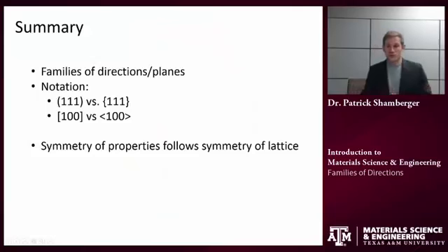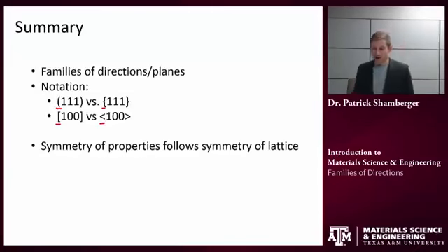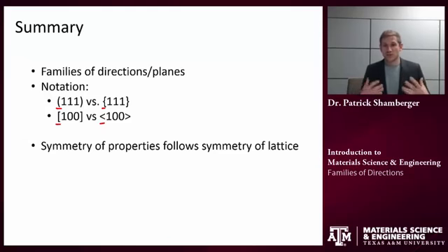Okay, so just in review, we've talked about families of directions and planes. We talked about notation, so round versus squiggly brackets for planes, square versus angular brackets for directions. And most importantly, we talked about how the symmetry of properties follows the symmetry of that lattice.